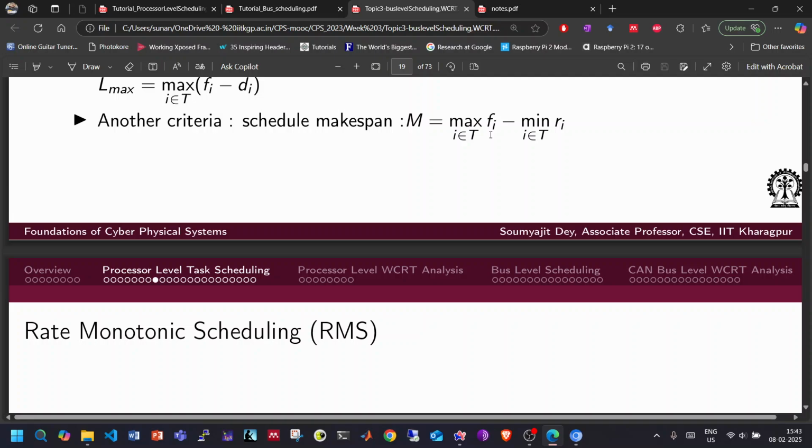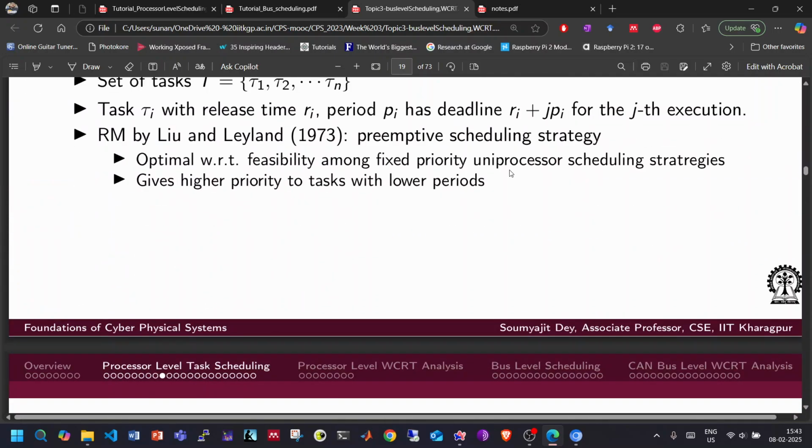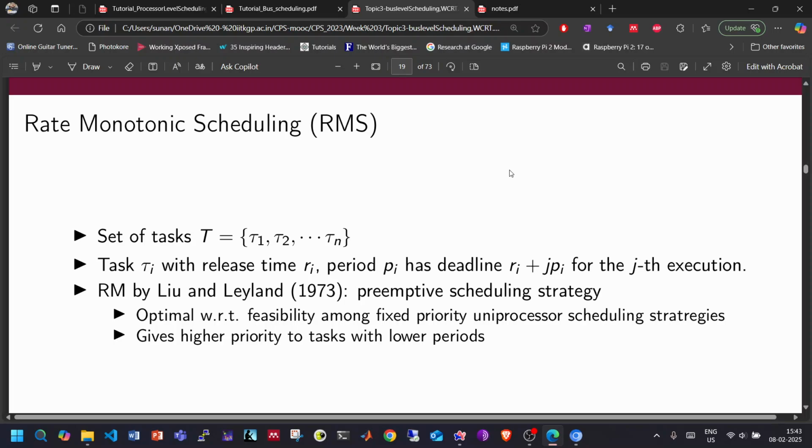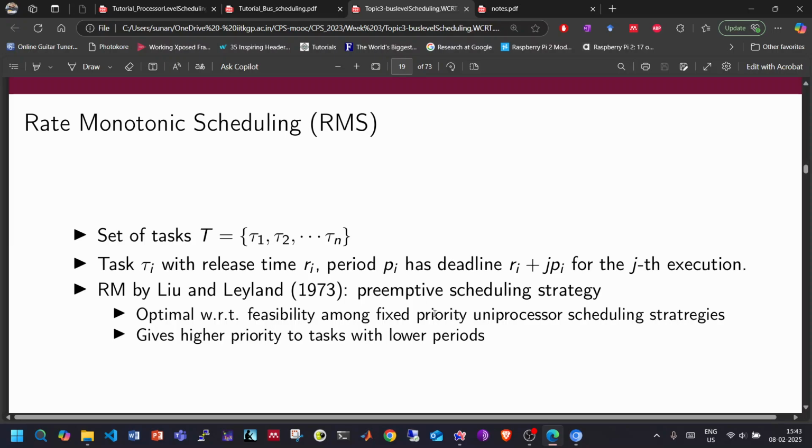We will see now how we make a scheduling policy for that. Consider there is a set of tasks. In this set, there are n tasks. They have a periodicity of p_i, and the periodicity is always considered as the deadline. As I was saying, these are considered implicit deadlines of a task. When the task is periodic, the periodicities are considered implicit deadlines.